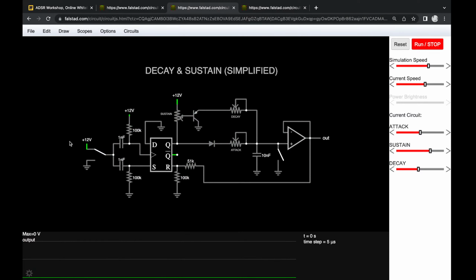All right. So just to explain this, we still have our input key here. We have our high-pass filter that is connected to the set input. We have our little weird kind of high-pass that generates an upward slope on key down to the clock input, with the data input tied low. These things just reset the flip-flop whenever the key goes up. And then we have our attack phase here. So we go through the output, through the pot into the capacitor.